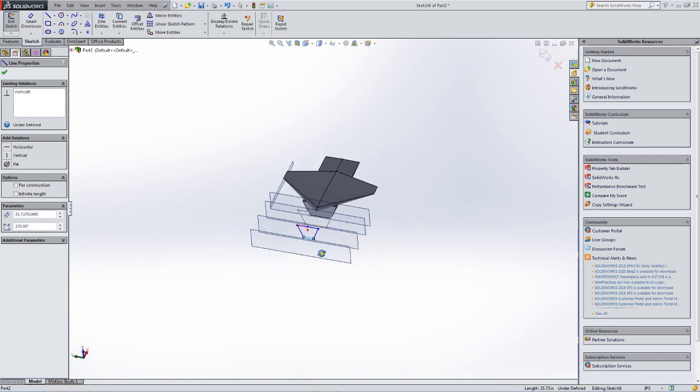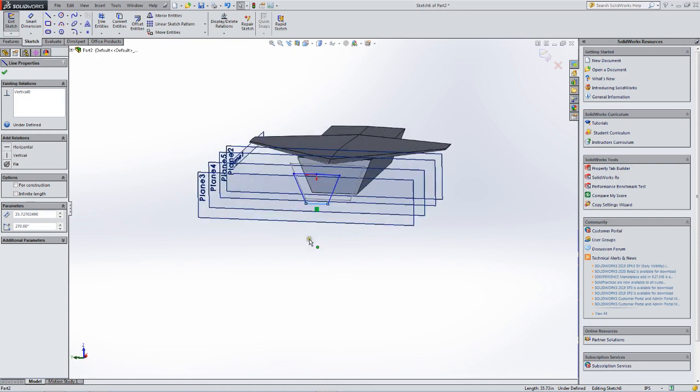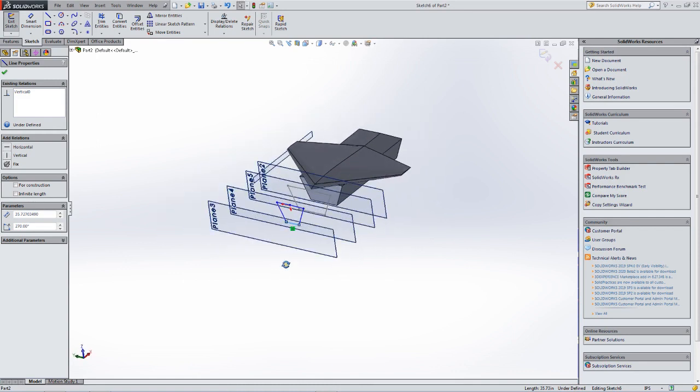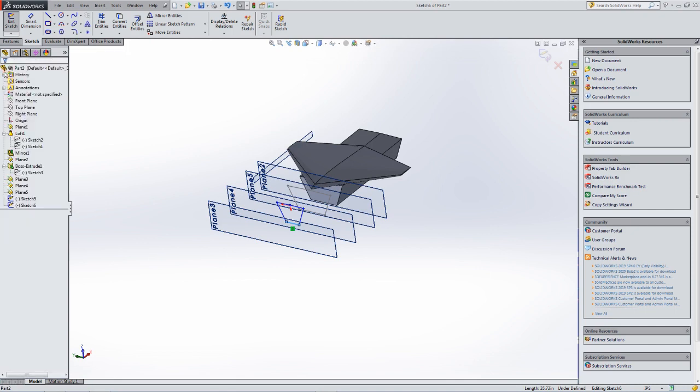And then the last thing I'm going to do, well, I've got 2 more planes. Even though the right plane is not showing, that's where the nose of the aircraft is. That's the 0 coordinate. So I'm going to do one more shape like that and then taper it down to the nose. Hit the check box, exit sketch. Sketch is good. I'm going to copy sketch 6 and put it on plane 3.